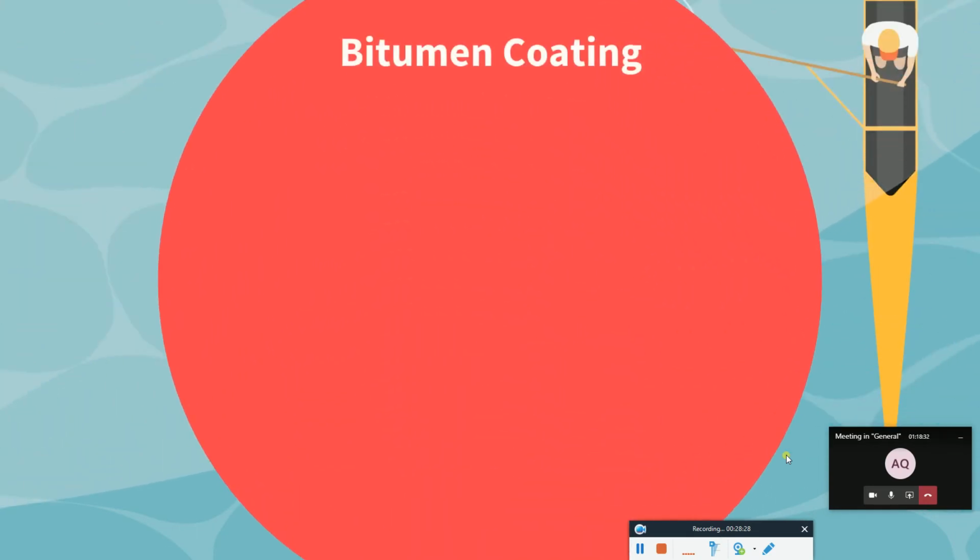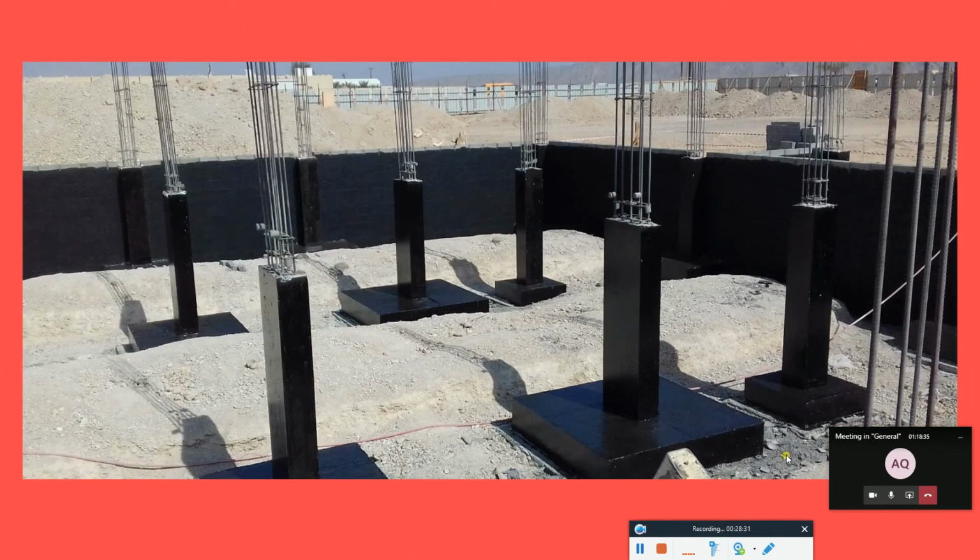Now this is the coating. This is the bitumen coating that we have talked about. You can see here we have the substructure, and then we have the blockwork, the solid blockwork, and this is what we said. In case of any contact with the soil in the substructure zone, we need to apply the coating. This coating will ensure that there will not be any chemical reaction between the soil and the foundation.